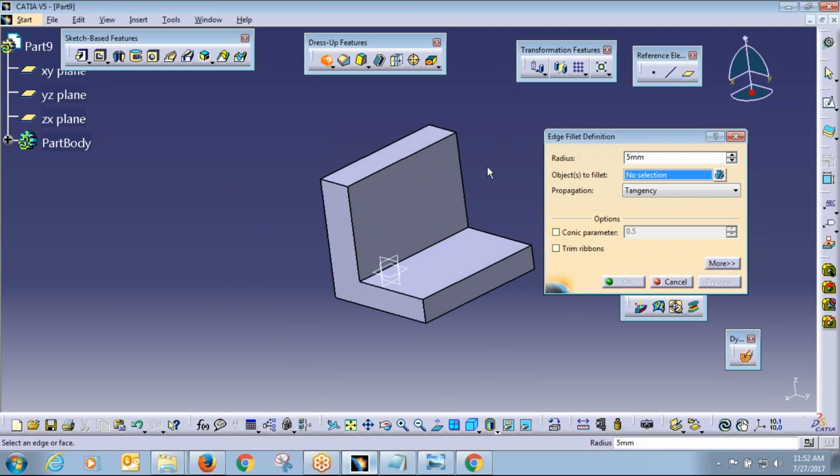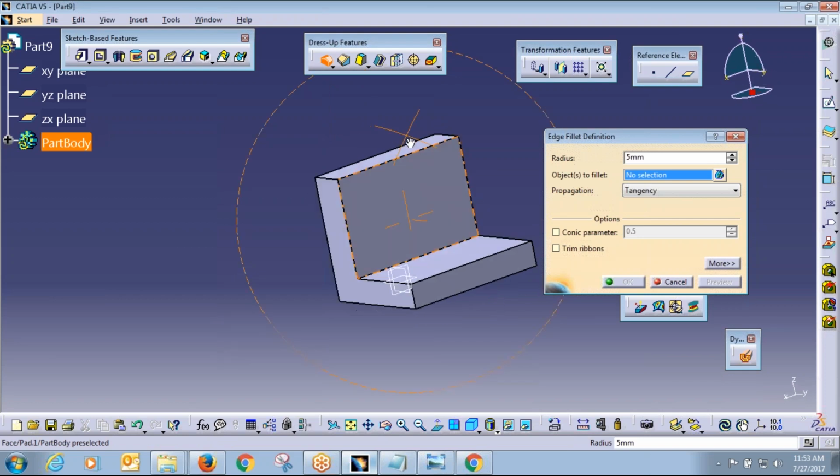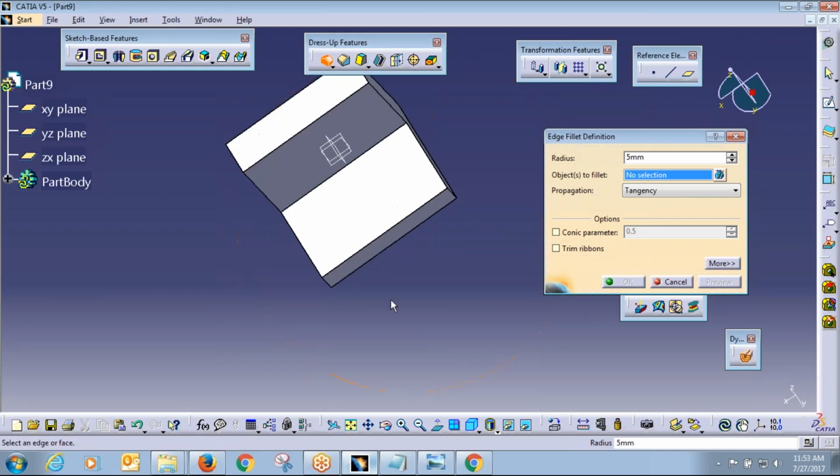For manufacturing components as well, if the parts are cast or molded components, fillets help in easy removal from the mold or dies. So always it helps to remove the part from the mold. So for that also we use fillets. There are the fillets and these drafts. They are very important functionalities to give. So we'll see what are the different options available.